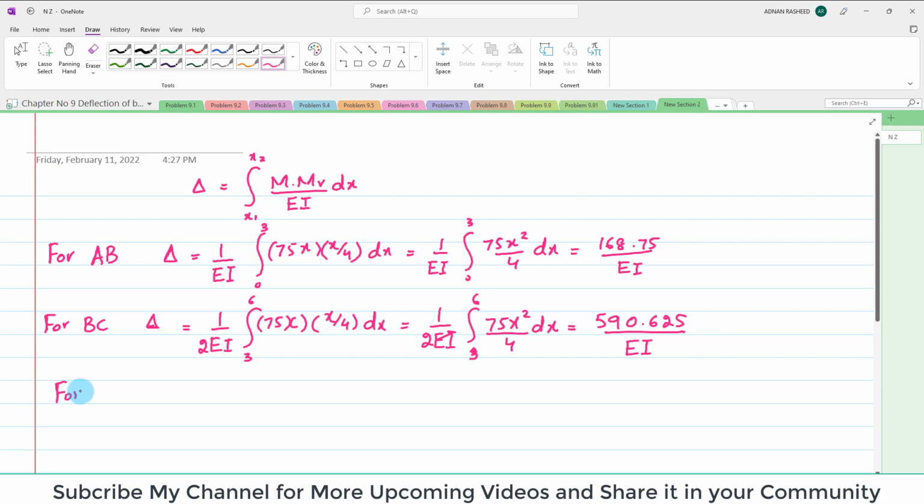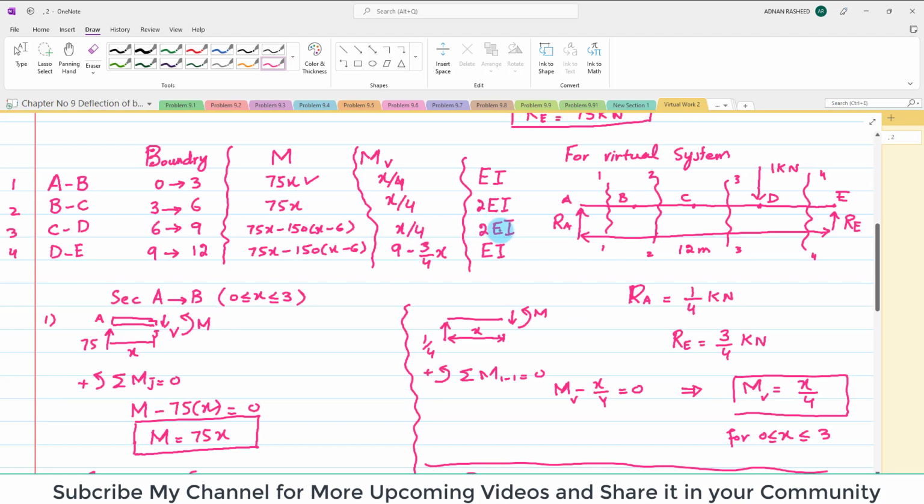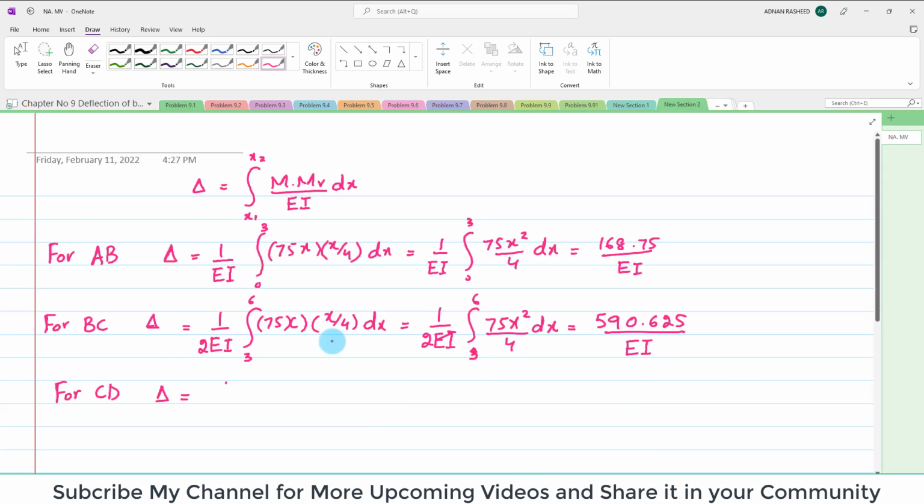For portion C to D, we can also calculate, and it will be equal to the integral of m into mv dx over EI. For portion C to D, you can see again this EI is 2 times EI, and the moment equation is this, and the virtual moment is this. So put the value over here. So 1 over 2 EI, integral of, now the limit will be from 6 to 9, and the moment equation is 75x minus 150 into x minus 6.